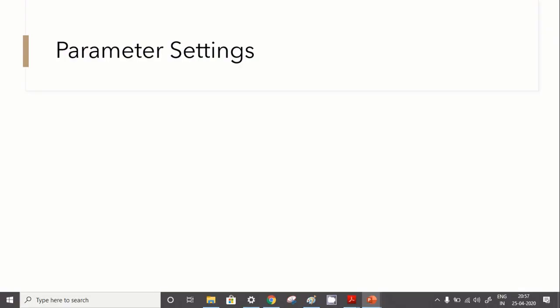So now we are into the section of parameter settings, which is a very important section, because whatever problems we find in the visibility at the server side, we always see that there is an issue in the configuration, or we can say in the parameter settings. Because of that we either get zero values or negative readings, or if the configuration itself is not there, we just get a dash value. That means no value is coming in the kWh or in the diesel fuel stock, run hours, and we cannot measure anything.